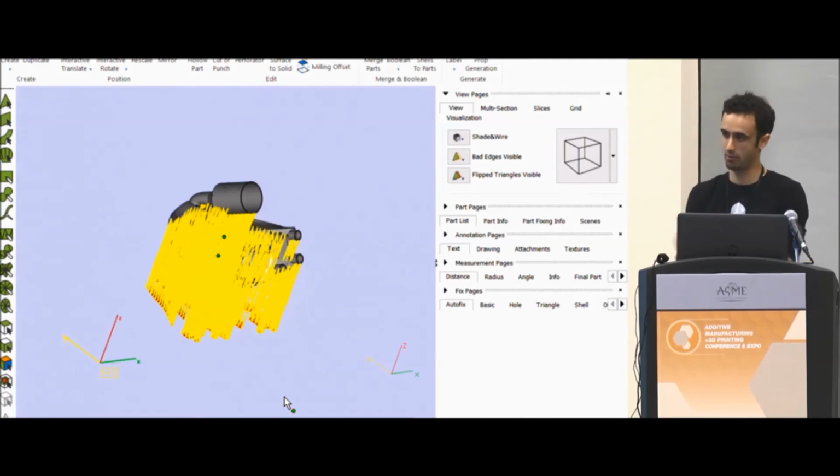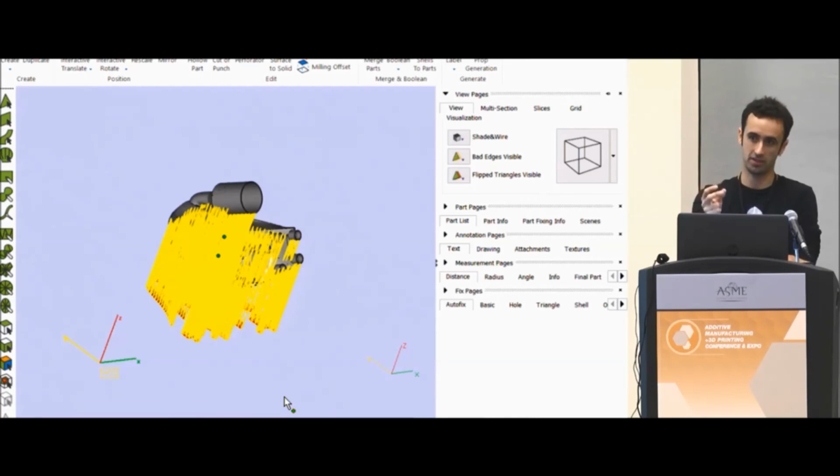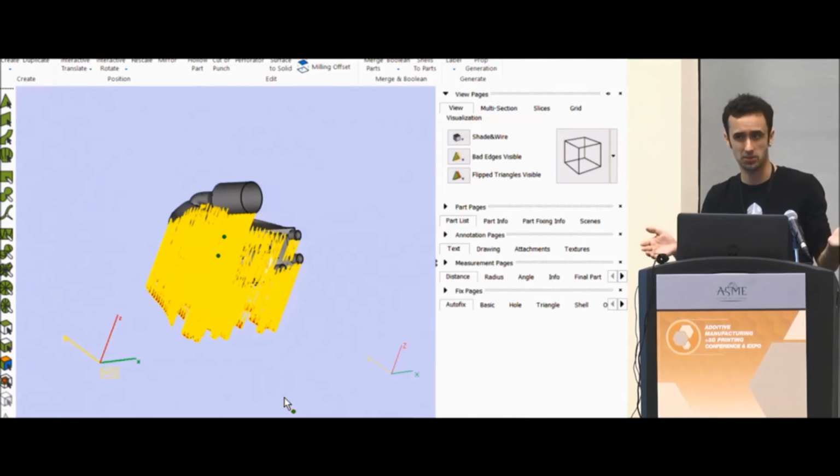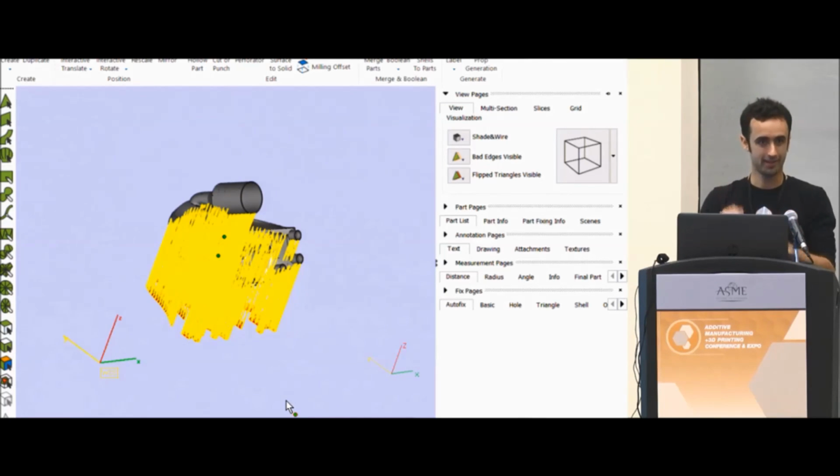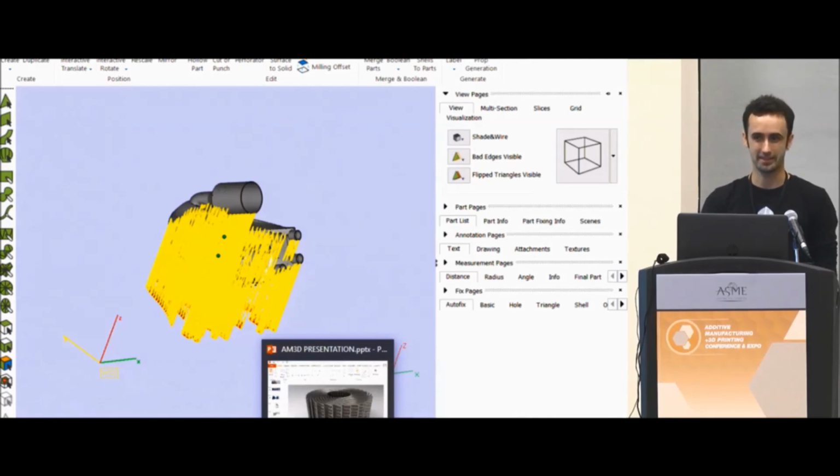But to get to the point where that one part is perfect, oriented correctly and supported correctly, and they get the desired result, probably took 30 or 40 tries beforehand to figure out what exactly was the best thing. Sometimes it's worth it up front to print this 5 or 6 times and break it. I break a lot of parts immediately. I pull it out of the machine and break it instantly. Now I don't have a part to show the client, but at least I knew where it broke and how to fix it for the next time. And so that's one of our techniques.